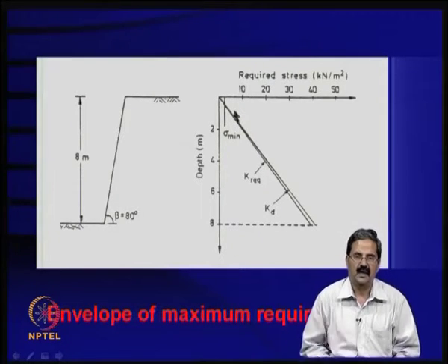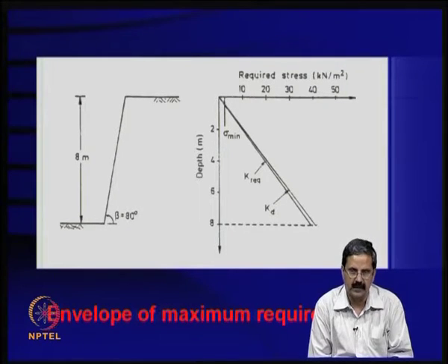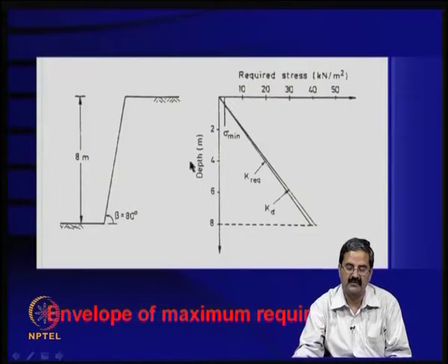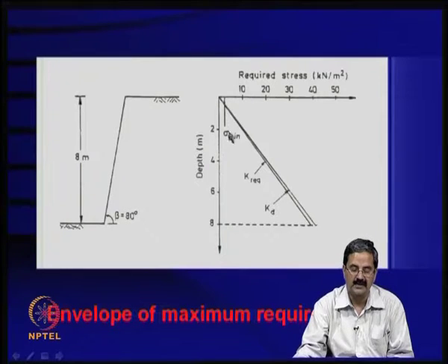If you remember, I showed in the compaction chapter the amount of pre-stress that the materials have. For example, in the case of clays there is a lot of pre-stress, but in the case of sands it could be lower. That pre-stress value one can get from here, maybe make some correction and then use it here, if you are using compaction. If you are not compacting, it is fine, you need some minimum stress because of the bond considerations. So, this is K required and K design, and then minimum stress values.